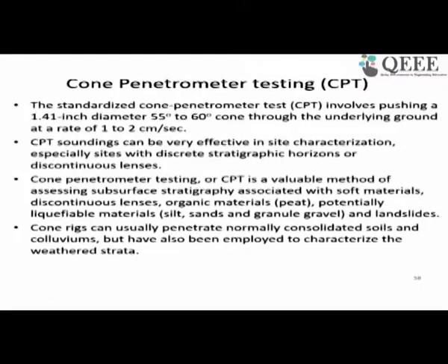In this method, a cone is mechanically penetrated in the ground continuously and the data is recorded. The cone penetrometer, as you see, is basically a small cone, 1.4 inch diameter with a cone angle of 55 to 60 degree. This CPT testing is very effective in site characterization, especially sites with discrete stratigraphy.